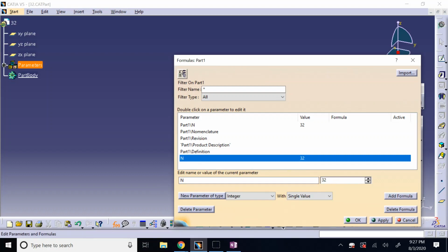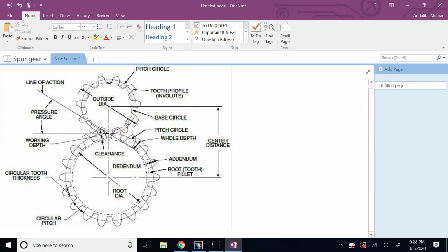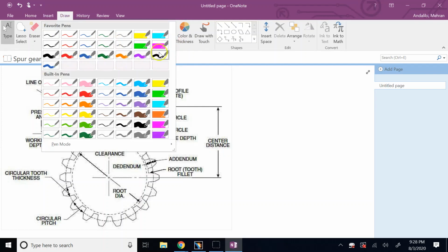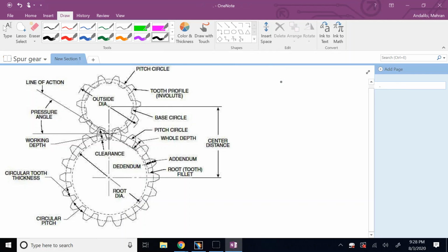The next parameter that you need in a gear is called diametric or diametral pitch, P. Okay, and the meaning of diametral pitch is, so here these are two gears that are meshed together and work together, and as I said, the meaning of diametral pitch, which is 1 over the gear modulus, so diametral pitch P is basically the number of teeth in the gear n divided by the diameter of this imaginary circle, which we call the pitch circle.